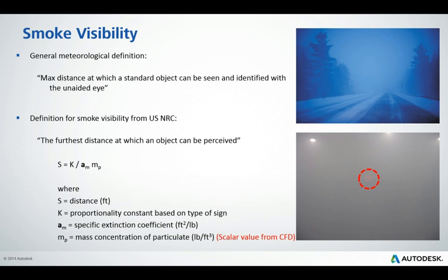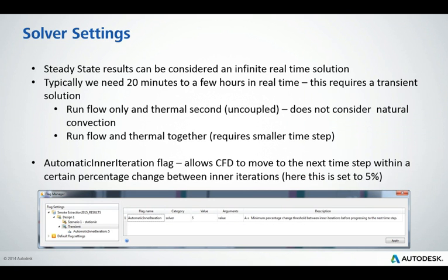Always we would want to run these models as transient. Obviously a steady state analysis assumes essentially an infinite runtime, which can generally mean that... fires almost always burn for a finite amount of time, for say 20 minutes. And what we found is that we can utilize a flag to help optimize the solver process.